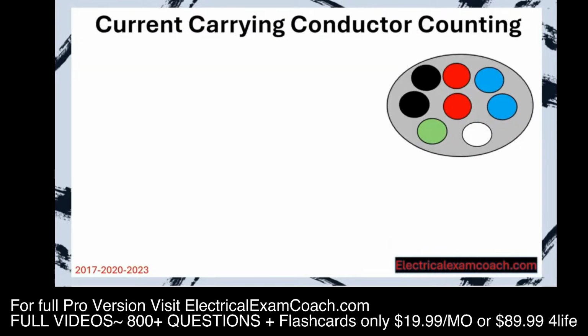Now let's learn about current carrying conductor counting, because we're only going to be counting the current carrying conductors. You may get a question on your exam that gives you the number of conductors. That's easy. You're going to go to the tables and do the math. But you may get a question on your exam that asks you, in a scenario of wires, how many of them are current carrying conductors? The first one's easy. All ungrounded conductors. All of the hots are going to be considered current carrying conductors under normal circumstances.